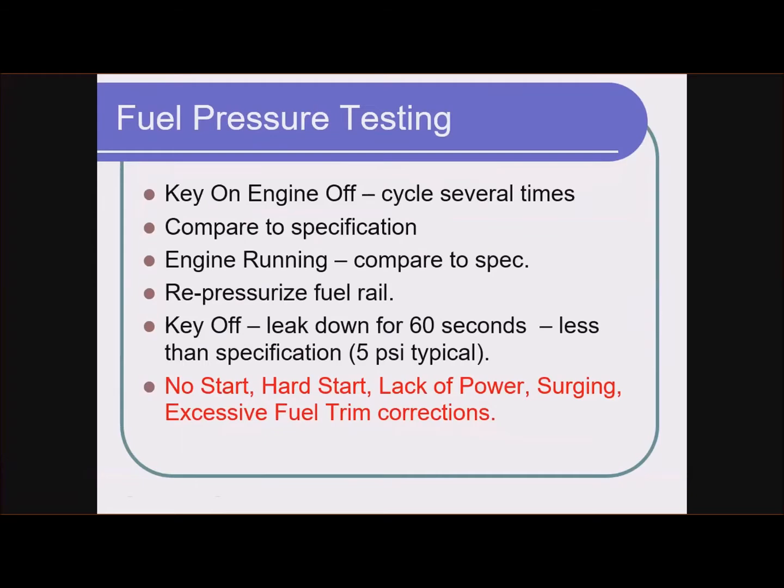when you go to restart the car, it won't start until the fuel pump runs, pumps fuel up into that rail, and the pressure gets high enough to start the vehicle. So that could be a long crank time. Instead of starting instantly, it might crank for 3, 4, 5, 10 seconds while we fill up that fuel rail. So that's what we're testing for when we turn the key off and watch the leak down.